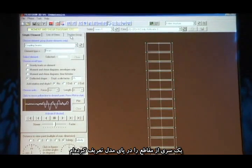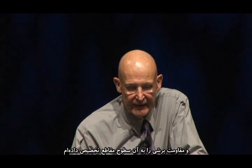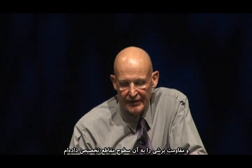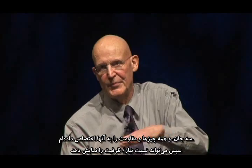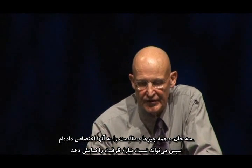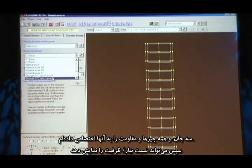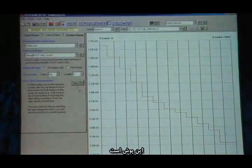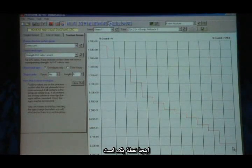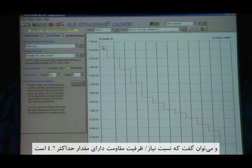What I've done here is defined a series of sections at the base, first story, second story, etc., all the way up. And I have assigned shear strengths to those cross sections. And they're through the complete wall, so 3 webs and everything. And I've assigned strength to them, and it can plot the strength demand capacity ratio. And I can plot that. And this is the envelope, and this is what it looks like. And here's 1.0. And what this one says is the strength demand capacity ratio reaches a maximum of 1.7.